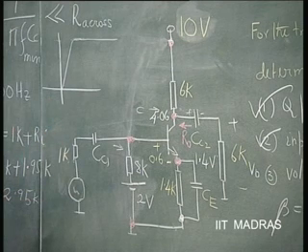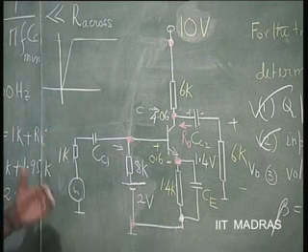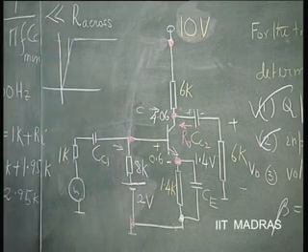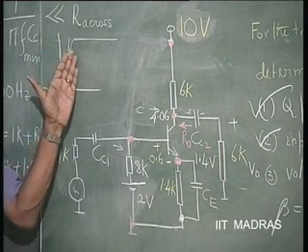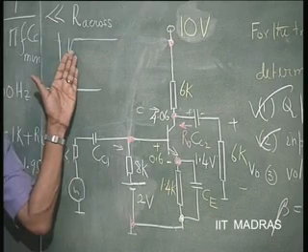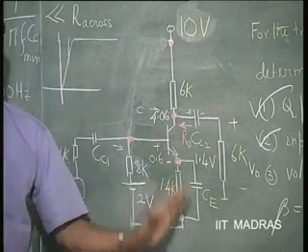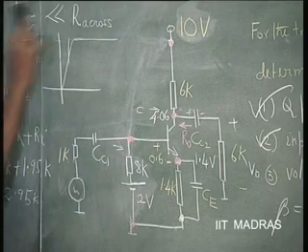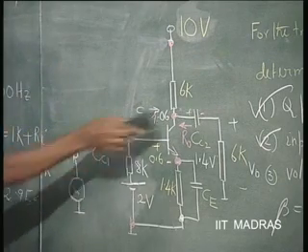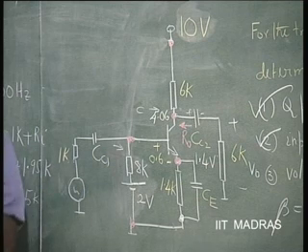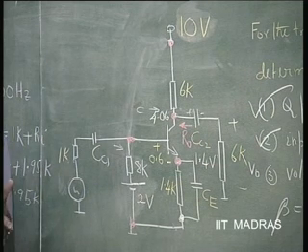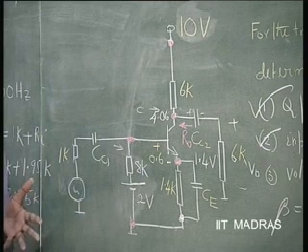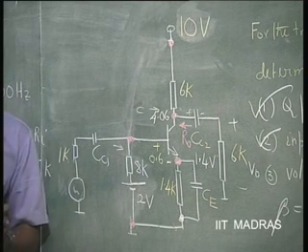Thereafter, it will come down to 0 as you approach the DC. So, that brings about a lower cutoff frequency. Therefore, the lower cutoff frequency in an amplifier is always determined by these capacitors. Now, you can select any one of the capacitors to determine the lower cutoff frequency exactly. Other capacitors are designed to be short circuits. So, that is the way design is done.